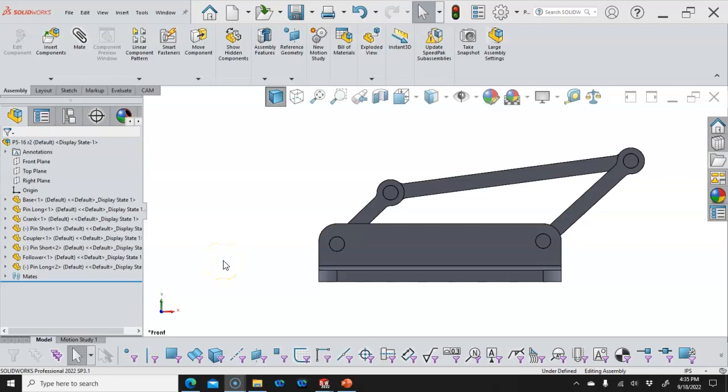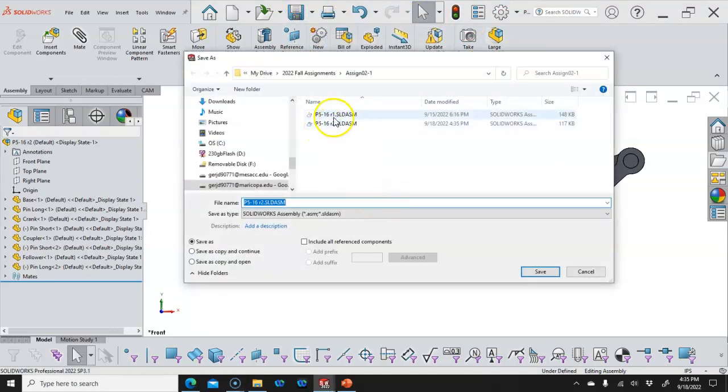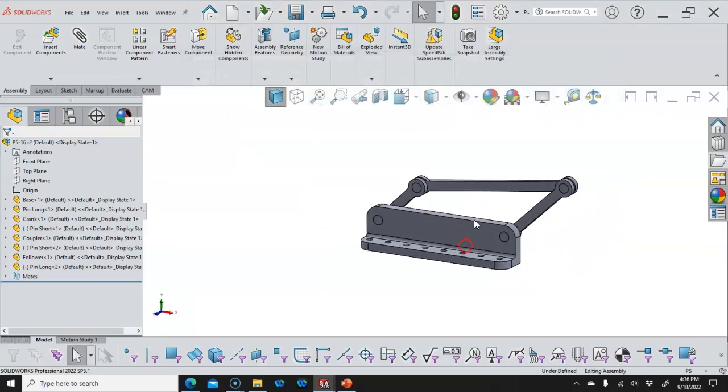So one of the Windows rules, as well as the SolidWorks rules, is that we can't have parts or assemblies with the same name. If we do, we can't use them in the assembly. It has to resolve the naming. So when I named this, I just called it revision 2. Revision 1 was my practice piece, and we can save that as an R2.